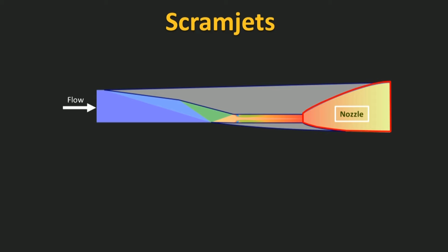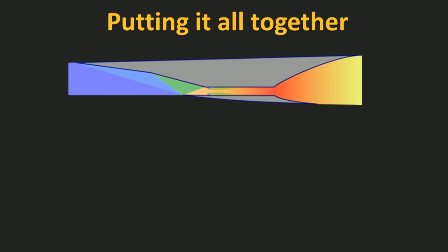This is a nice, simple model of a scramjet engine, but it has all the components that we need to investigate the fundamentals of hypersonics and of scramjets. The engine layout here is the backbone of the course. This is what I mean. In section 2 of the course, we're going to start by analysing the type of flow that occurs in the nozzle. It may seem strange to start at the exit of the engine, but the regime of flow occurring there is fundamental to all compressible flows. This flow regime is called isentropic flow.